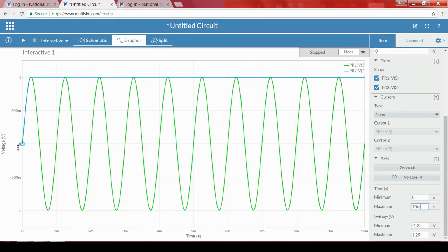If we observe, the output initially keeps on increasing, meaning the capacitor starts charging, and it is charged to a value of 1. Why only to 1? Because the peak input voltage that we applied is only 1 volt, and since we do not have any discharging path, the capacitor stays at this particular point.